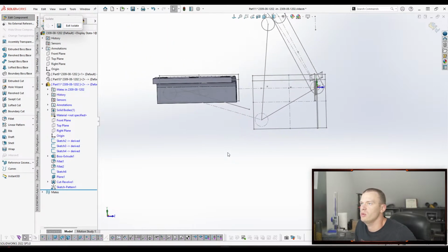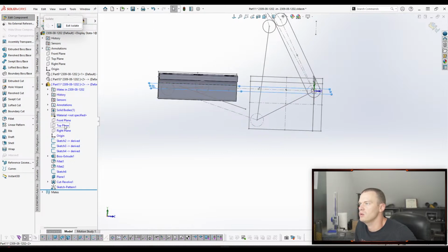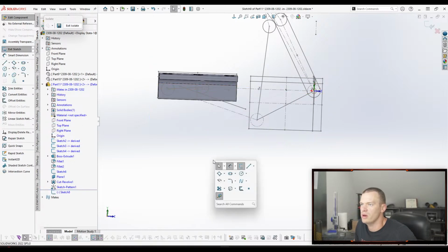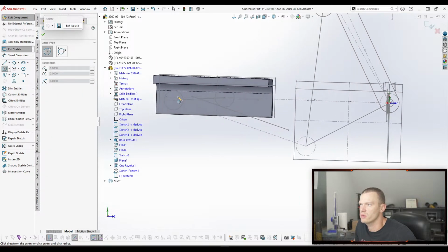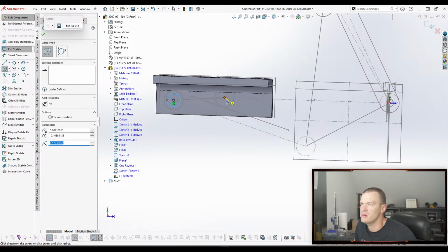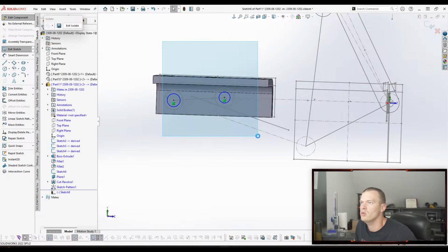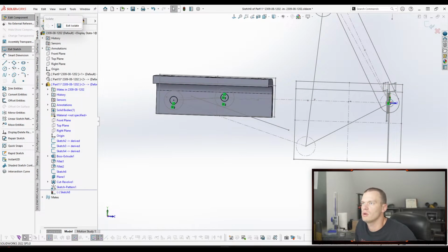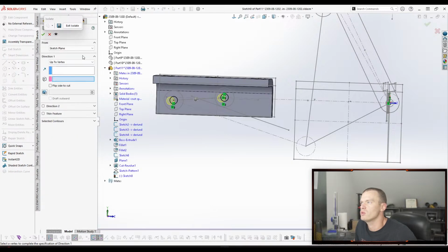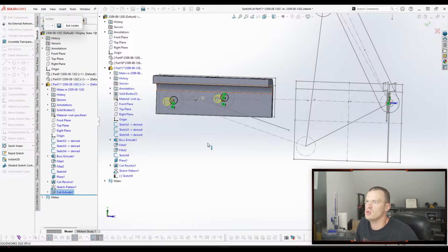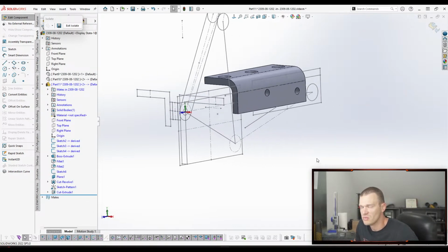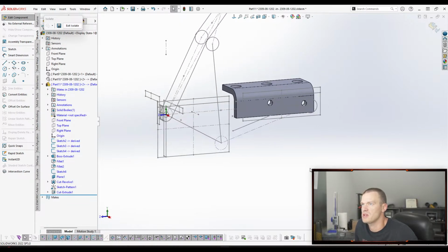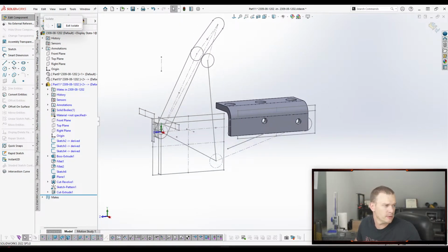All right, and now we need our side holes where our rivets are going to go through. And we know that our rivet size, or the hole for the rivet, is going to be equal to the diameter of this, which we looked up previously. And then that's an extrude. We're going to do through all, both. Use through all when possible, because it's pretty robust. Just make sure it's not cutting through something it's not supposed to.